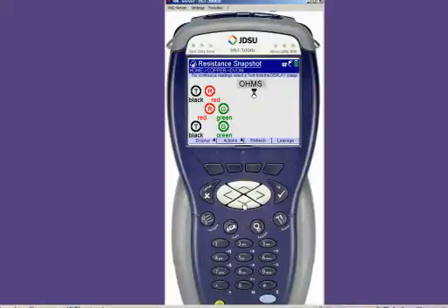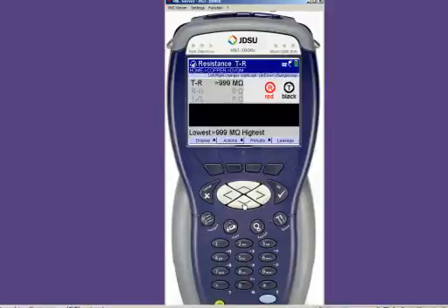However, it's resistance snapshot. So we discussed early on we're not crazy about snapshot. So if we hit down arrow again, we'll go to resistance continuous. Now, I don't want to appear as though I'm down on our snapshot measurement. The main reason for showing you what I just displayed was you did not have to wait for that resistance snapshot to finish, right? If you knew you wanted to go to the continuous, you just hit your down arrow button a second time and you would go there. So keep that in mind. You're running the tester. Don't let the tester run you.